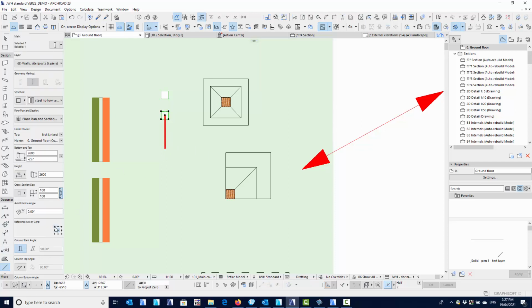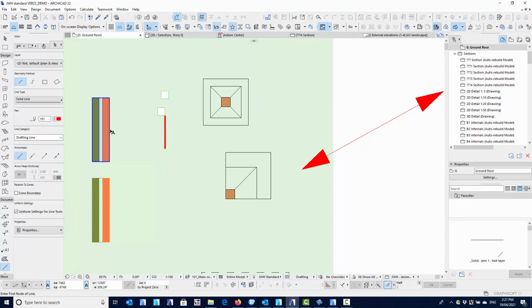and I change the axis point, reference axis location, you can see that the column moves, the axis point stays exactly where it was, so the reference line is in effect staying where it was and the column is physically moving. That's the same when you select a wall.